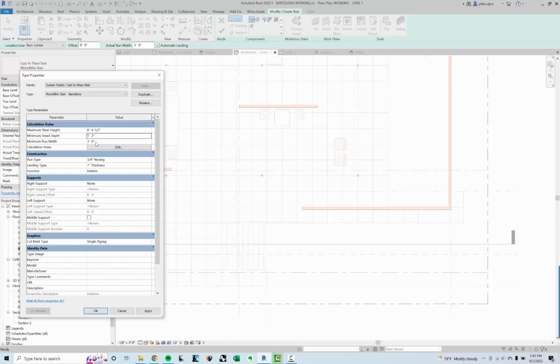Modeling existing stairs is a little tricky. This is really good for trying to figure out how stairs go from floor to floor. The defaults that it gives you is basically IBC standard. So if you start there, it's a good place, especially if you're not trying to do an ornamental stair, you're just trying to do like a fire stair or a code compliance stair. That's the good way to do it. Okay, so let's just set this for now, and if we want to change it, we can.